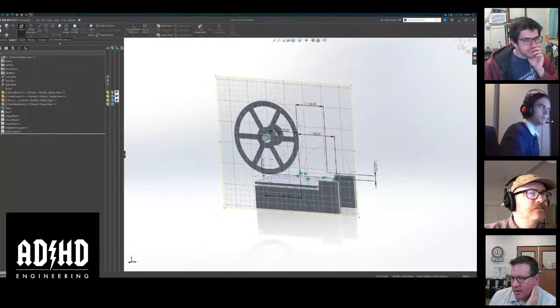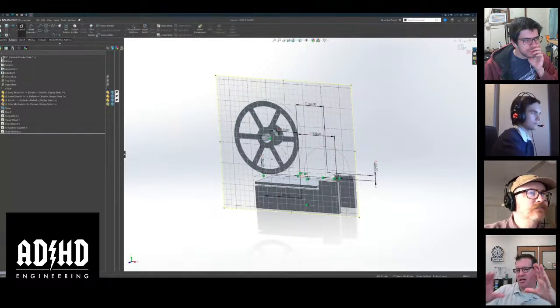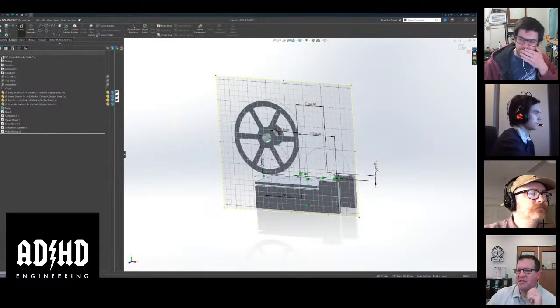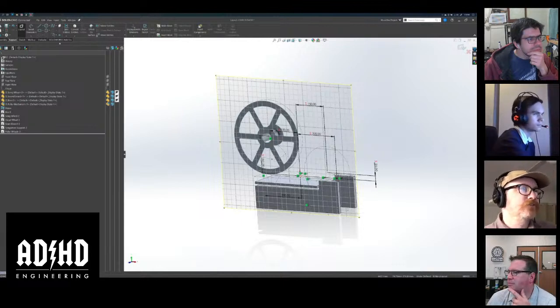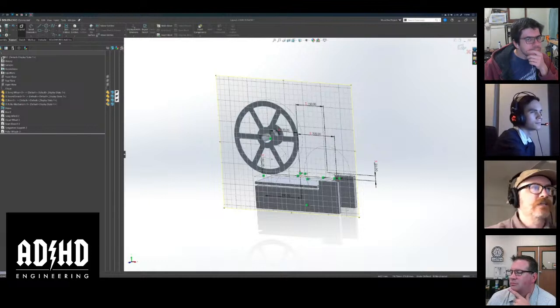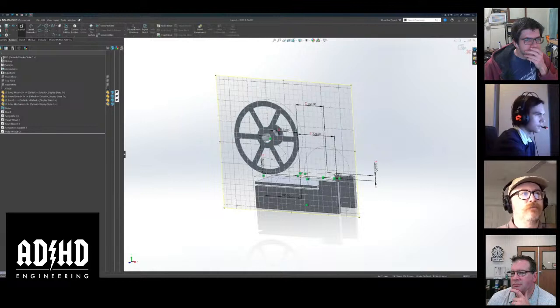So for the MMX, that would be our left plane, right? If our skeleton is looking at the axes of all the different shafts? I think it would be the top plane. I think in the MMX because it's XY, and XY is like the ground essentially. Yeah, that's true. Right, because Z isn't the top on this. Yeah, so this is early on when we first started working with SolidWorks. I was telling Tim that it's maybe a good idea to settle early on what planes you consider to be what. Do we want Z to be up? Do we want Z to be towards the front?